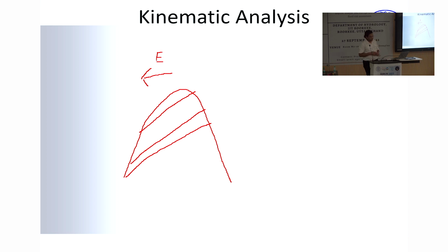So the beds are dipping towards east. Now we need to know 2 things. The angle of internal friction, you will get from geotechnicians or from us. We need to know the angle of the slope. So we change the color of the pen to green.